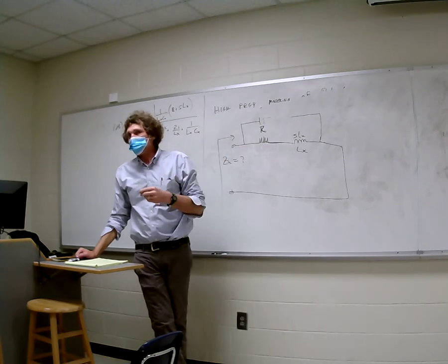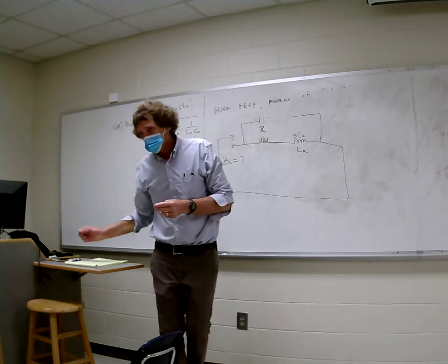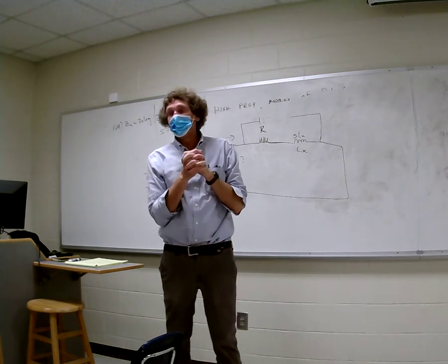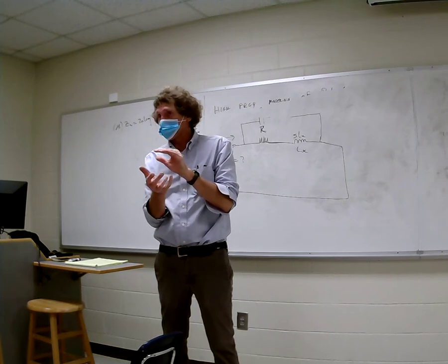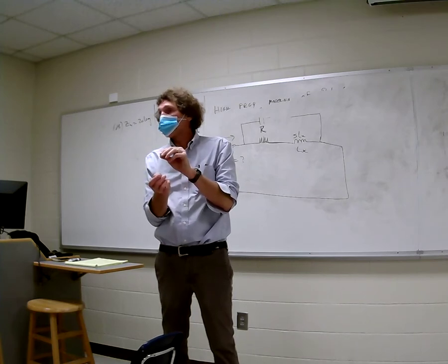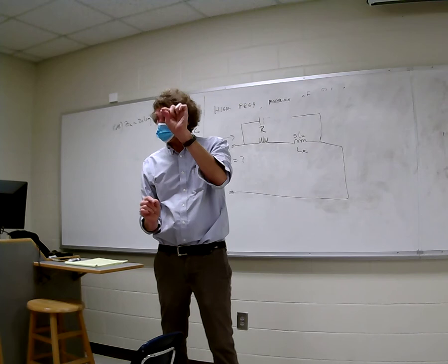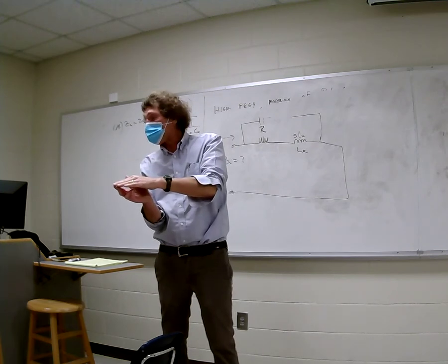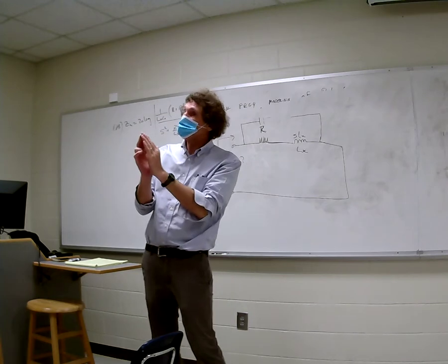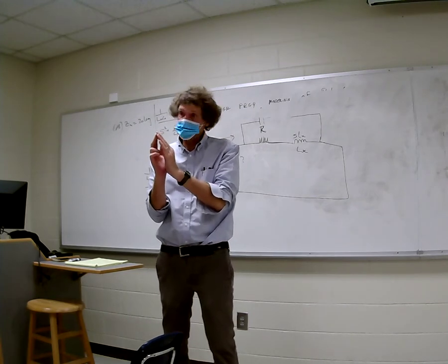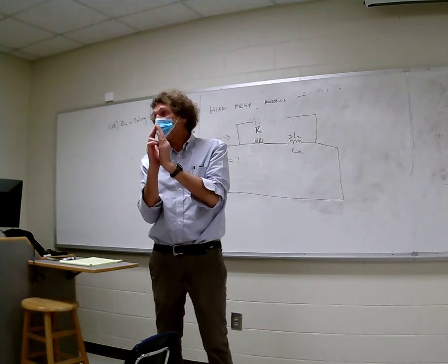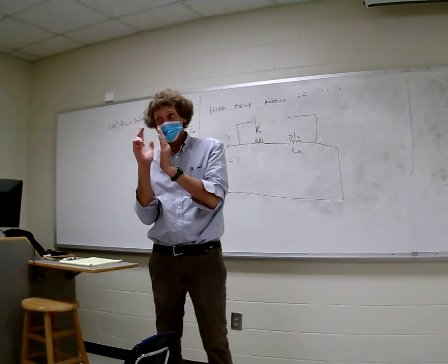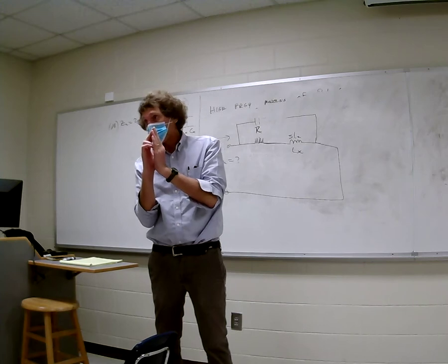When they talk about electrolytic capacitors, it's something that has an internal workings that's usually in a somewhat of a goo, I like to use that term, that is polarized. So if I put a plus to minus voltage, all the, you would call them dipole centers, will align in a certain direction. That's just the reality. Now, they don't change quickly. And if they do change, they generate a lot of heat. Keep this in mind. You don't want heat in a capacitor.